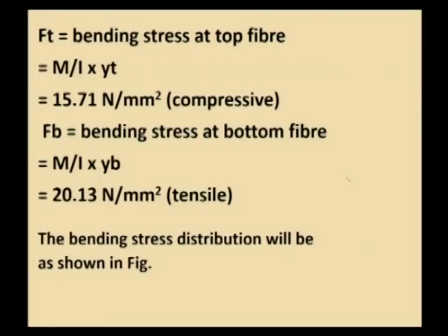So, we have values of bending moment M, we have computed the values of moment of inertia I, we know the values of y t and y b. So, substituting the values of M, I and y t and y b, we get stress of 15.71 Newton per mm squared at the top fiber and 20.13 Newton per mm squared tensile at the bottom fiber.